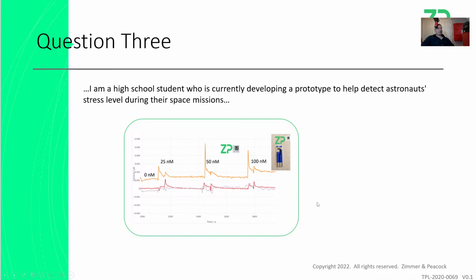What I can tell you is this is an electrochemical sensor. It's enzyme based. We're using a technique called amperometry, and it's really a repurposing of a glucose strip. At Walgreens and CVS, which are pharmacies in the US, you can buy glucose strips. Those are designed to discretely measure blood glucose, once off. We use that manufacturing technique, but we make a cortisol sensor from it. We change the enzyme, for example, and it's also designed to be continuous use, and you can see that here. So I apologize that we're not able to send them free.